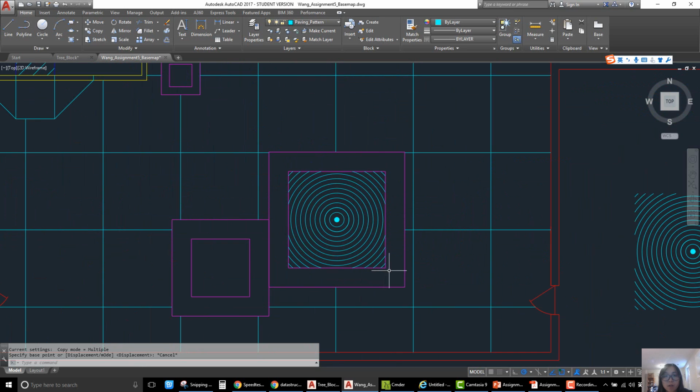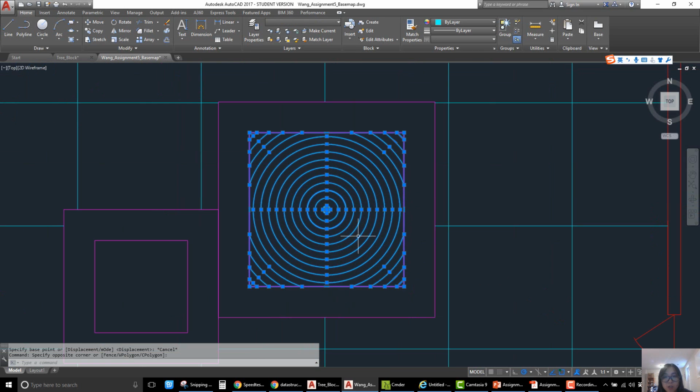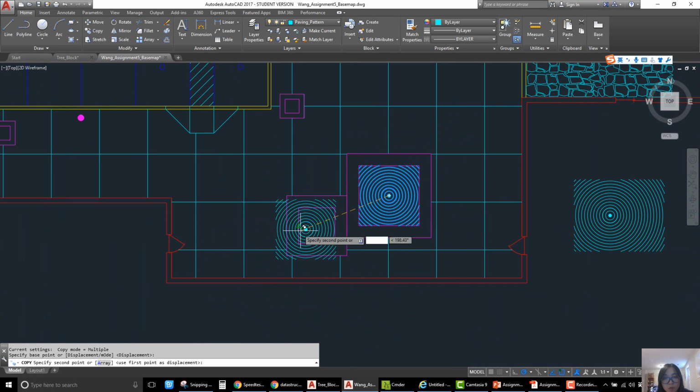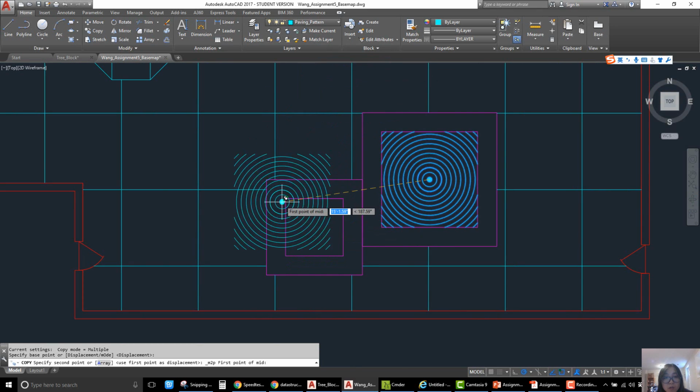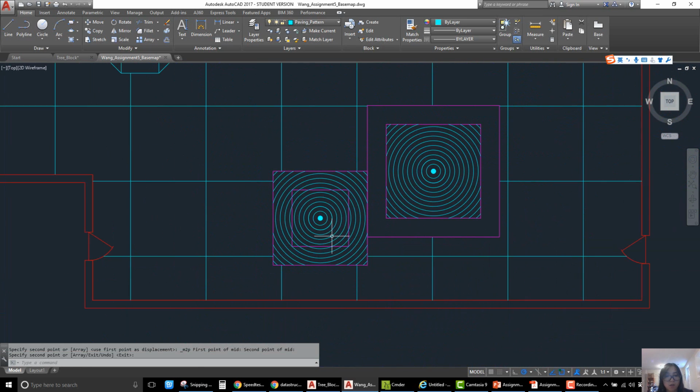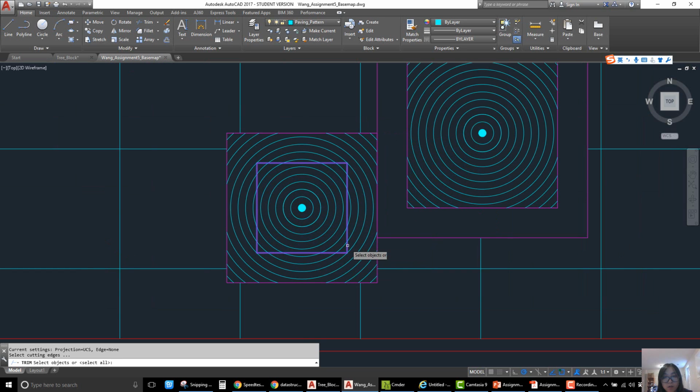Okay, I can copy this one, and I will shift and click this boundary and do copy from this to shift right click, mid between 2 points, point 1, point 2, okay, and then I will trim. For the rest of the lines, I will delete them.